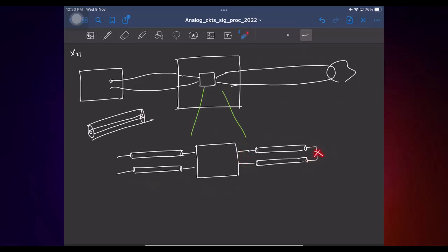The same holds good for the open circuit also, right? And say you apply some input, some voltage appears here, and if you think about it, the looking-in impedance has multiple resonances, right? Say you are measuring this parameter close to one resonant frequency, then the gain from here to here is going to be what? Yeah, it's going to be extremely large, right? So from here to here you will have a large gain.